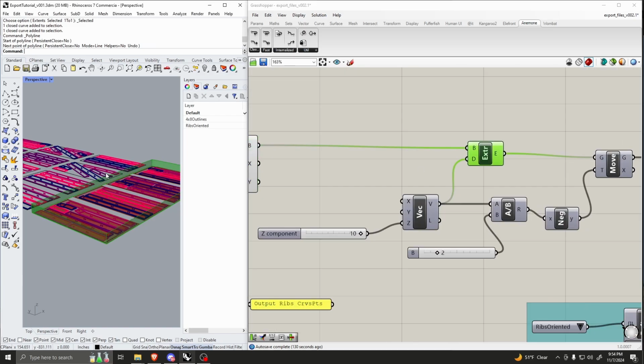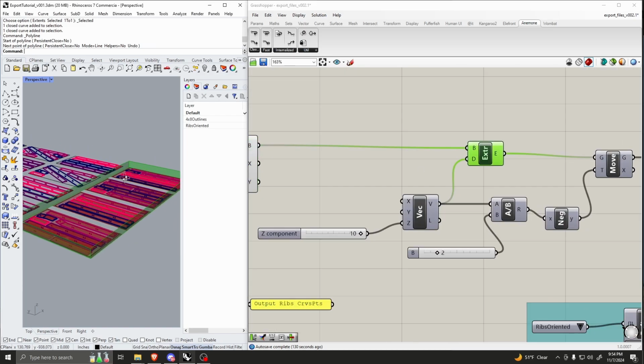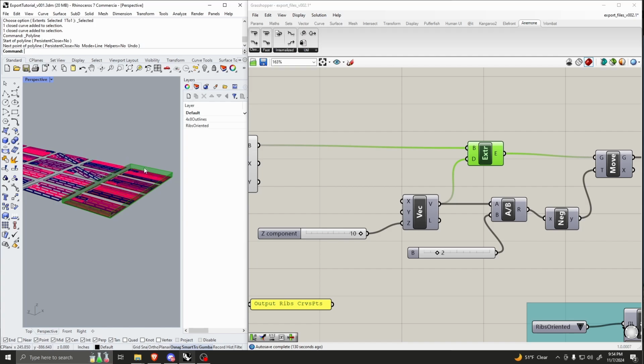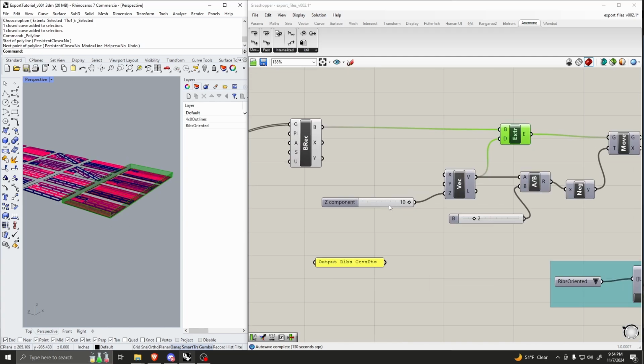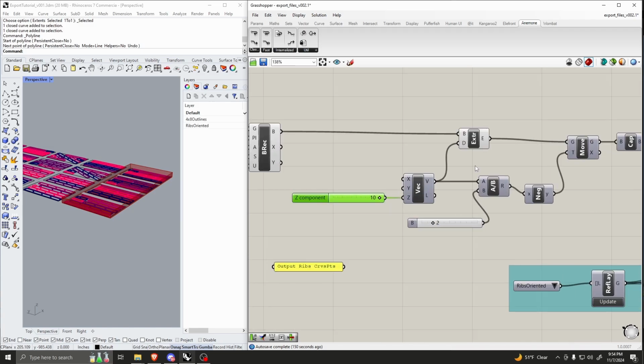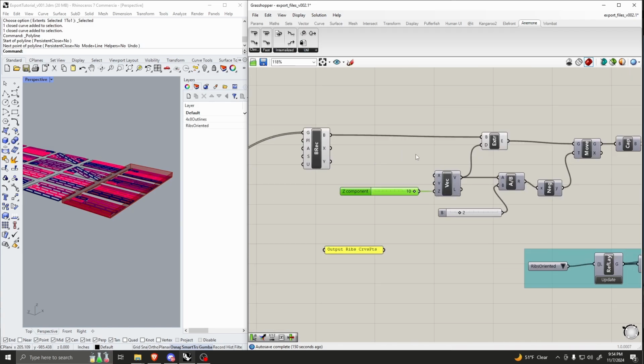And then I do an extrude because I want to create like a volume to capture all of my objects in. And obviously this is just kind of working for solid objects. If you have points or whatever, you'll have to amend for that, which is pretty easy to do, but this is just for solids. I'm sure you can figure that out too.